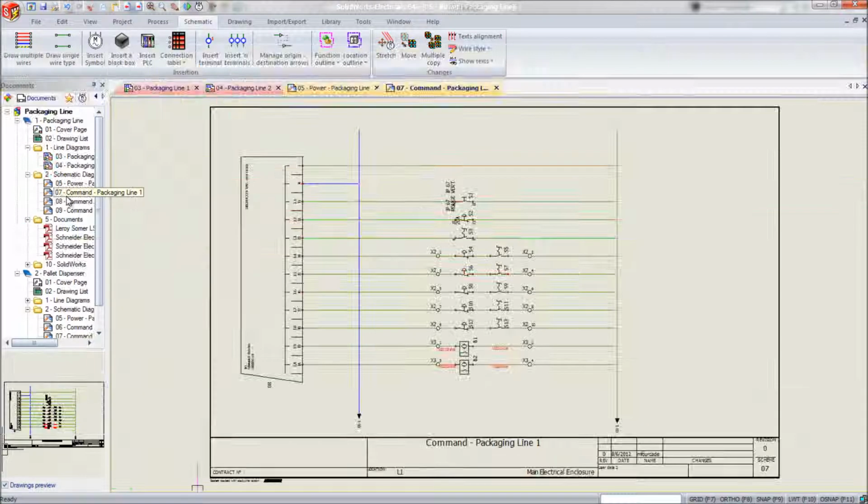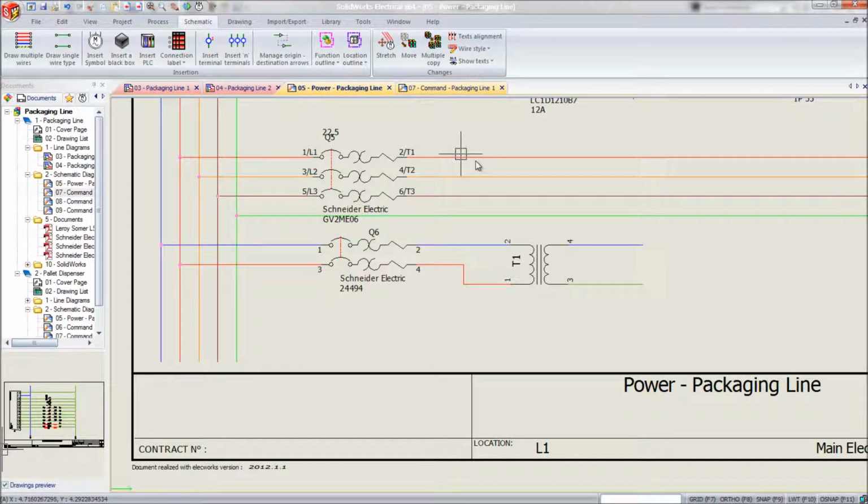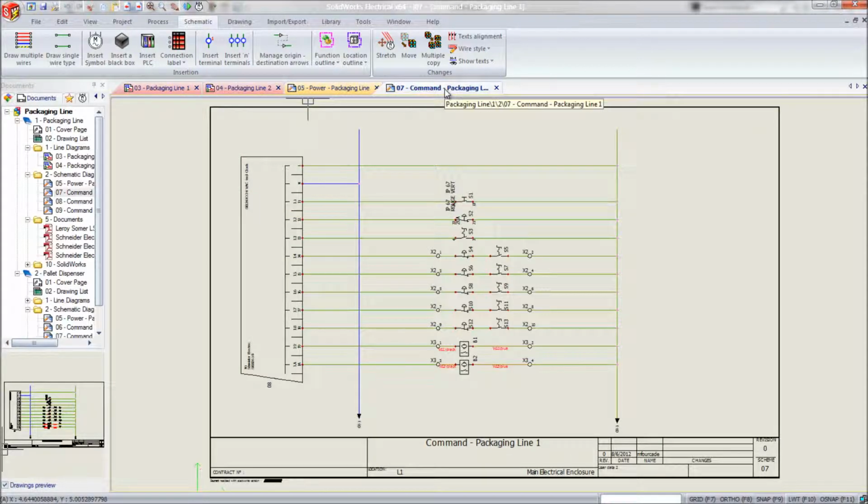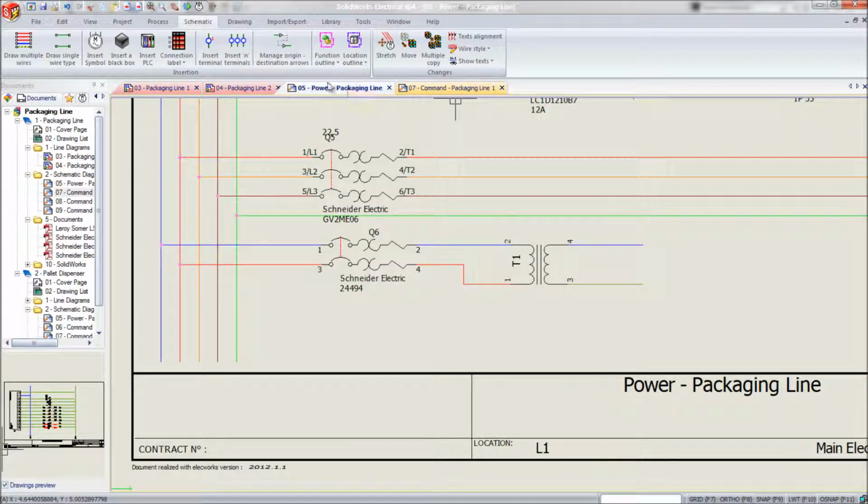With large electrical designs, the use of multiple pages for the schematic is a standard engineering practice. To maintain electrical connectivity and create a continuity link between circuits on different schematic pages, off-page circuit references are used. In the case of our example, the output of the transformer circuit needs to be linked to the PLC power input circuit on a different schematic page. To create this off-page connection link between circuits on different schematic drawings, the use of an off-page reference is necessary.